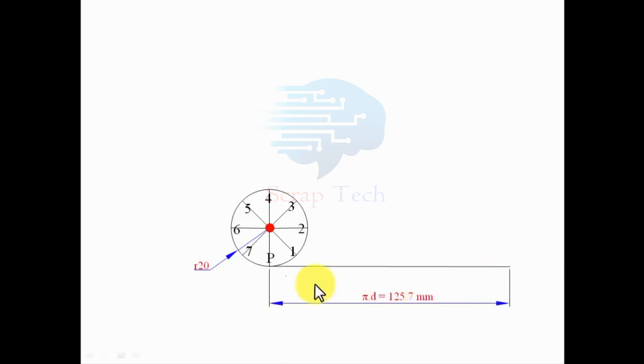Moving ahead, we're going to divide this line or string into 8 equal parts, and for that I'll be drawing a line from this point P, at any suitable angle and of any suitable length, like this. I'll be placing arcs of 1 centimeter radii like this, 8 arcs for 8 divisions. This particular point has to be joined with the end of this line, something like this. Keep your mini drafter along this line, tighten the screw, bring it to the 7th point, draw a line, bring it to the 6th point, draw a line. Keep on doing so until all the points have been exhausted, and finally you're going to realize that this string or this line has been divided into 8 equal parts. Let's name each and every one.